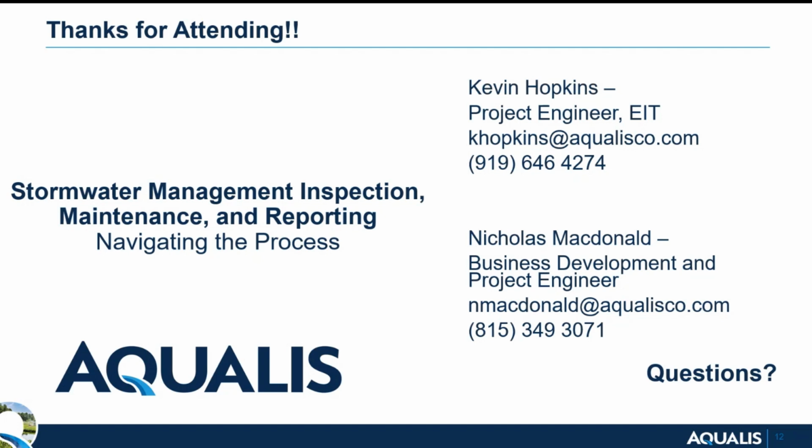Can you explain the need between an inspection during dry weather and then wet weather? The illicit discharge detection and elimination form I mentioned has to be performed during a dry weather period, either 48 or 72 hours after a rainfall, and the specific municipality will state what that requirement is.